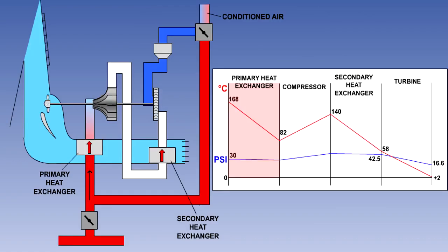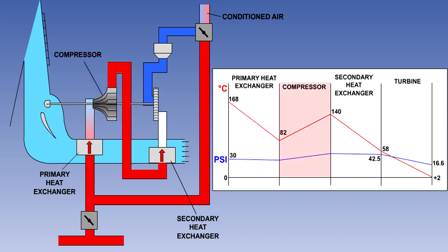The low-pressure bleed air, or air from a blower, is pre-cooled in the primary heat exchanger. Although the heat exchanger is very efficient, it can't cool the charge air down to a temperature lower than that of the ambient ram air, which in some situations may be as warm as 40+ degrees Celsius. The cooled bleed air then has its pressure and temperature increased by the compressor.